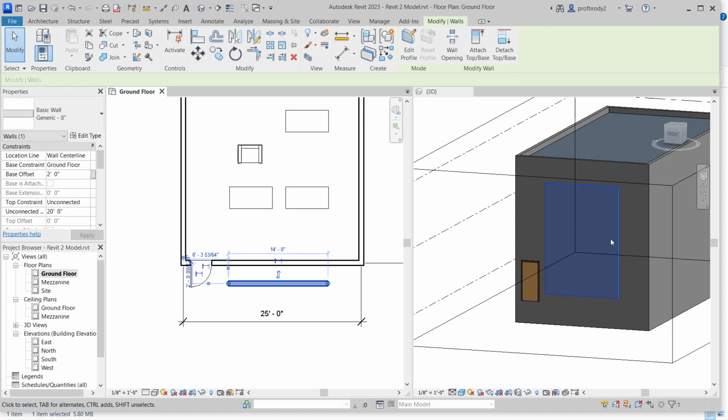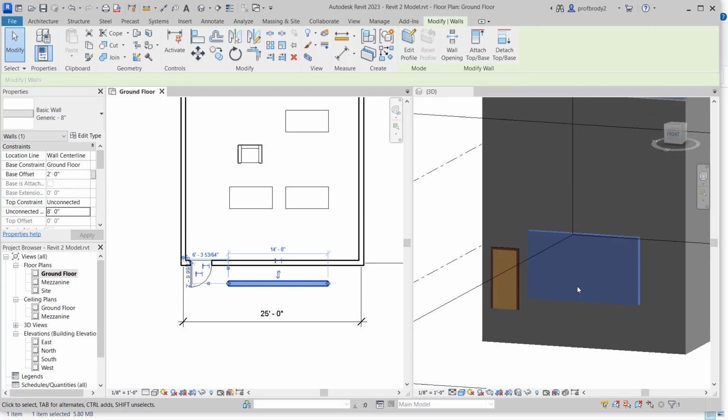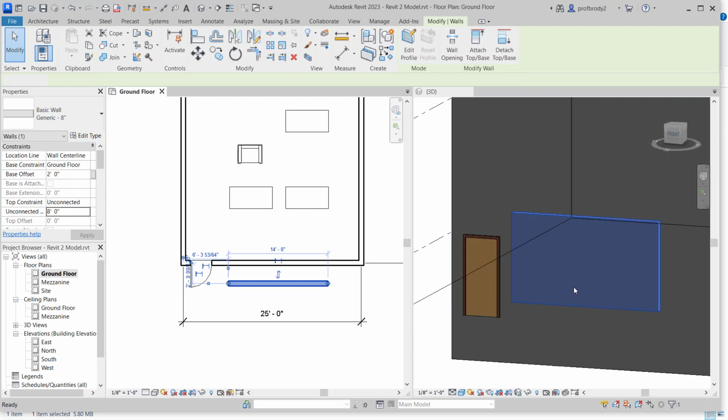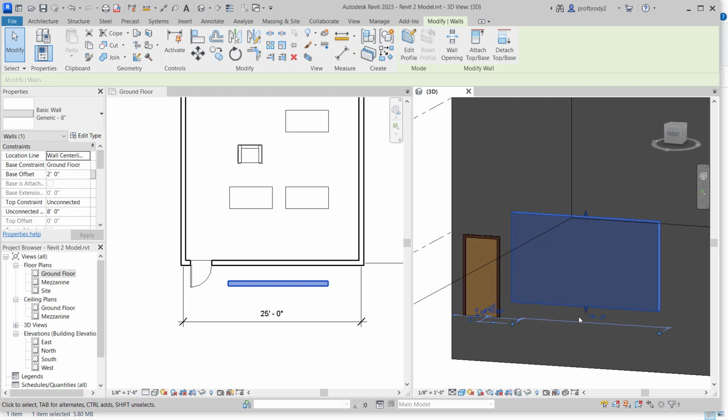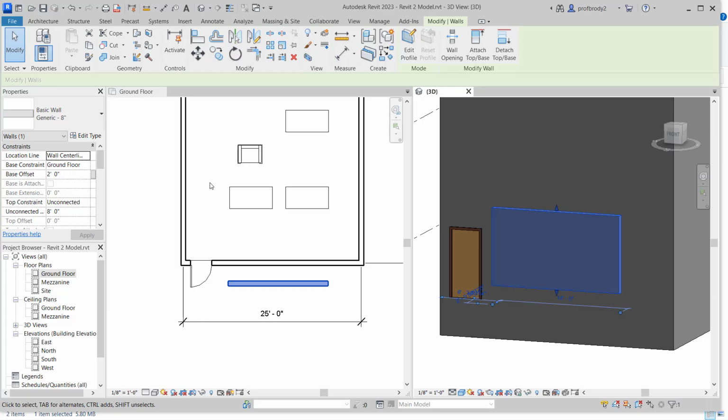If you hit apply, you can see the wall move. And I can also make it a specific height. I think we'd like something really nice and tall, maybe 8 feet. And I'll just hit enter or apply here, and like magic, you can see in this view that the wall is created. Now you might say that doesn't look like a storefront window, now does it?